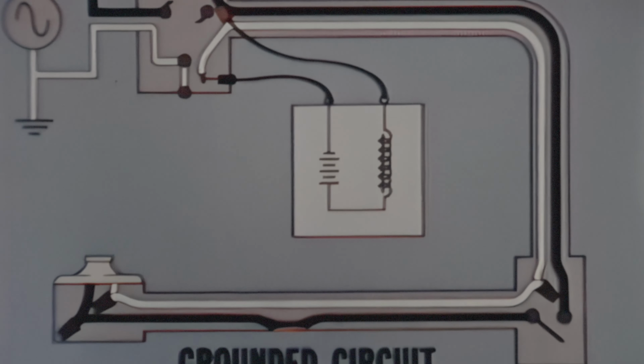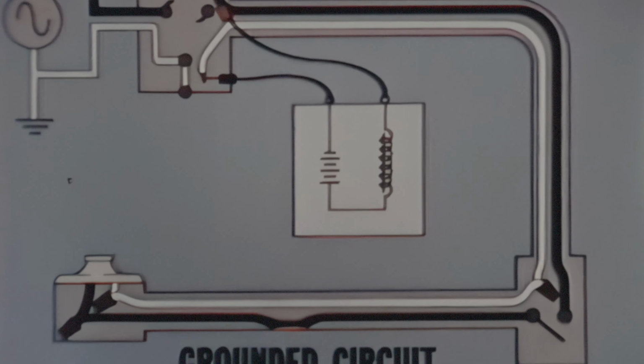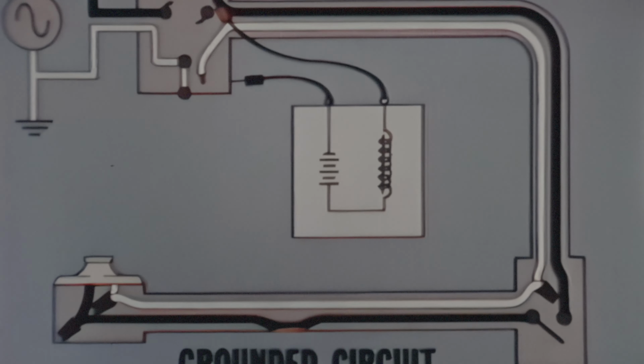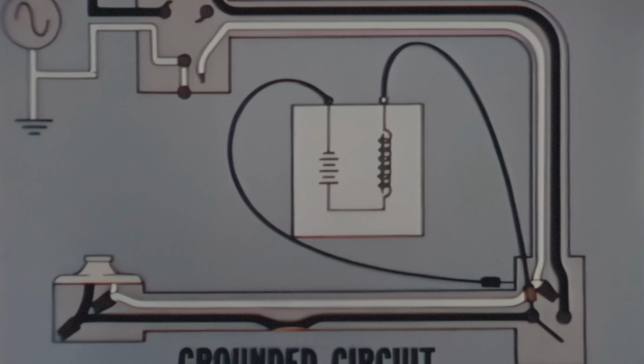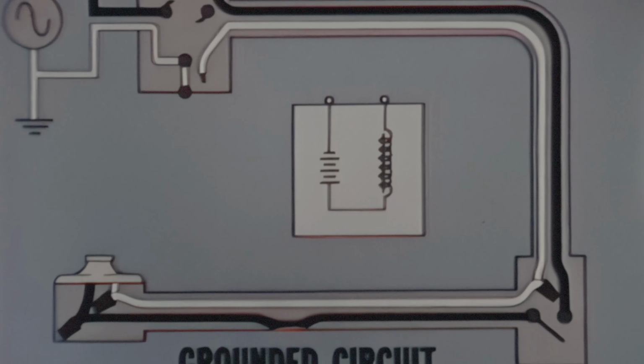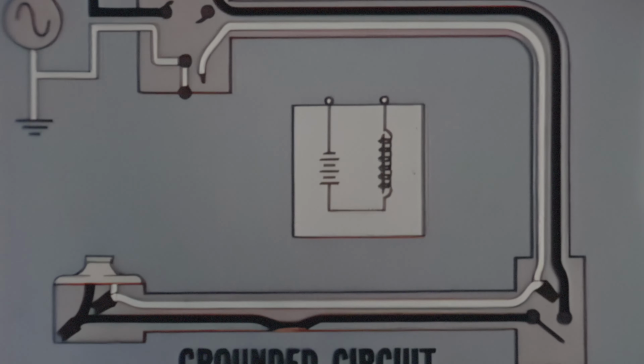First, checking between the two conductors indicates that there is no short circuit in the first section of the circuit. And there is no continuity between the hot conductor and ground in this section. However, between the hot conductor and ground in the second section, there is continuity. Since this is the last section, the testing is complete. In a longer circuit, the diagnosis would be confirmed by checking the next connection.